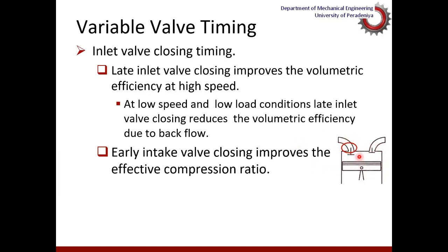Accordingly, if you keep the valve open at the bottom dead center of the piston during the intake stroke, then the compression ratio of the engine drops because these small areas open here should be included in the clearance volume. So the larger clearance volume leads to a smaller compression ratio.